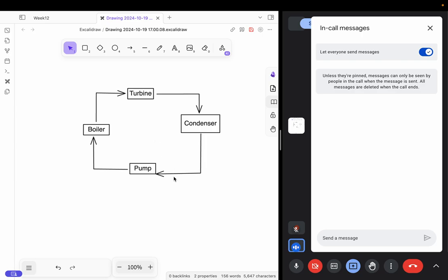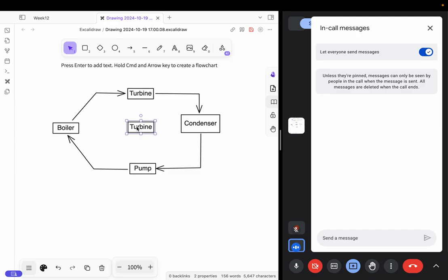Now what happens in regeneration? A part of the turbine outlet, which is actually going to the condenser, will actually be used, because whatever is the output of your turbine will be at a high temperature. So what we want to do is use this high temperature stream so that you can reduce the amount of heat you supply to the boiler. So we introduce something called a heater. This is my boiler. So I'll introduce a heater in between.